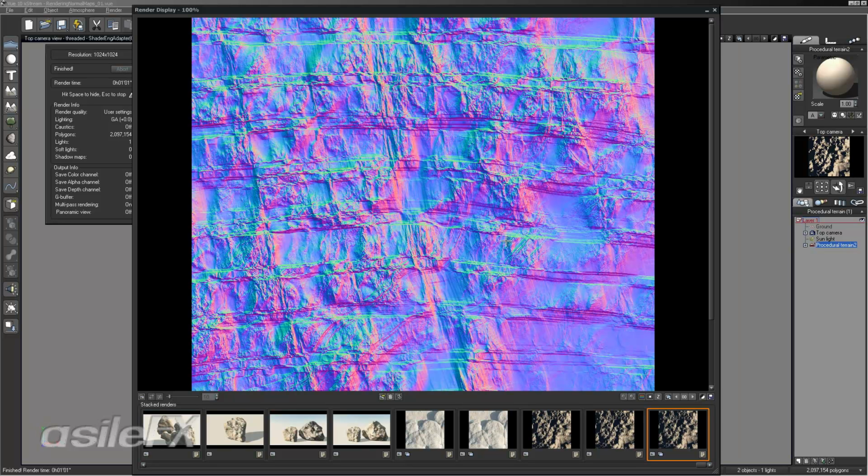To save this out as a 32-bit or 16-bit image, we are going to have to use specific formats. I do want to use the PNG format for the final output, but that's going to be done in Photoshop because you can't really save out a 16-bit output from View in the PNG format. You do have to use another format first. So we can use a TIFF format or a PSD format for that. And we could also do a 32-bit image, but a 16-bit should be way more than enough.